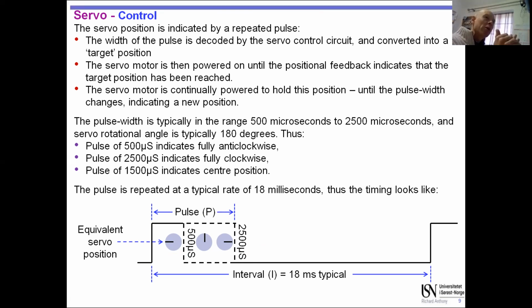It's very slow. You can't expect to send a pulse that would maybe end here and then the servo to get there, and then the next pulse. So the idea is that by having only a short range of pulses here in the whole range of possible pulse widths, you allow the servo to adjust before the next pulse comes in, right?